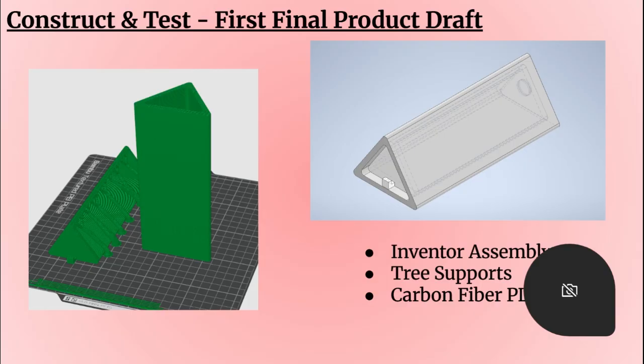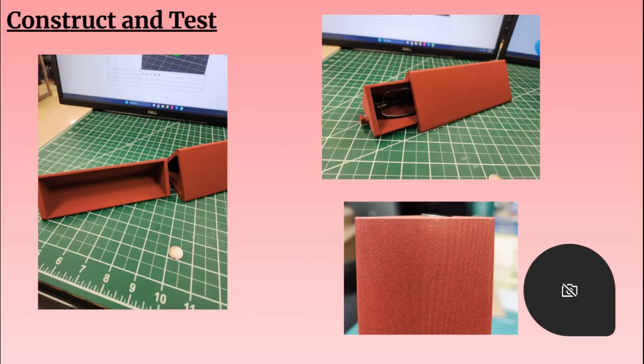So what I had to do in order to get the magnet inside the hole was to program a pause in the 3D print. The pause would happen right before the hole was done printing, but before the walls began being printed, which left an easy access point to the hole and continued the print after I was done putting the magnet in. Now, I wasn't able to do this myself. The print took longer than anticipated, and I had to go to my next class. So my teacher, Mr. West, had to insert the magnet in the shell for me. Thank you, Mr. West.